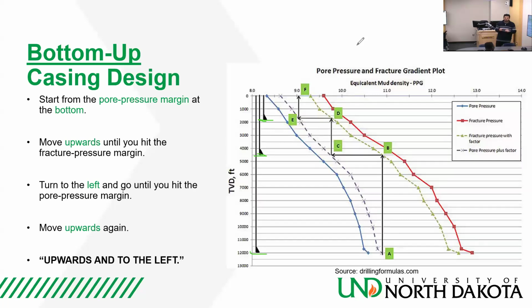Maybe you might mistakenly get close, then go and hit the pore pressure, where you can get a kick. Yeah, but if you want to be risky with the safety margin, you're going to get less casing string, less steel that you will need to put in the well.